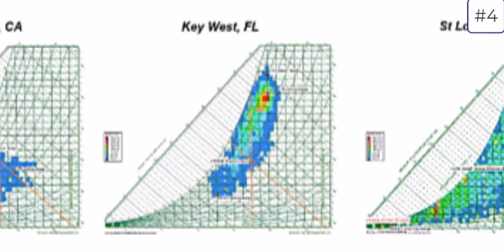We would start this by considering a reasonable zone temperature set point. For an office building, we might be trying to maintain 75 degrees Fahrenheit in cooling mode and assume something like 50 or 60% relative humidity. Now, over the course of a year, return air conditions will vary, but from a design standpoint, we would consider this set point not just as a point on the psych chart, but as a line of constant enthalpy from which to compare all potential outside air conditions.